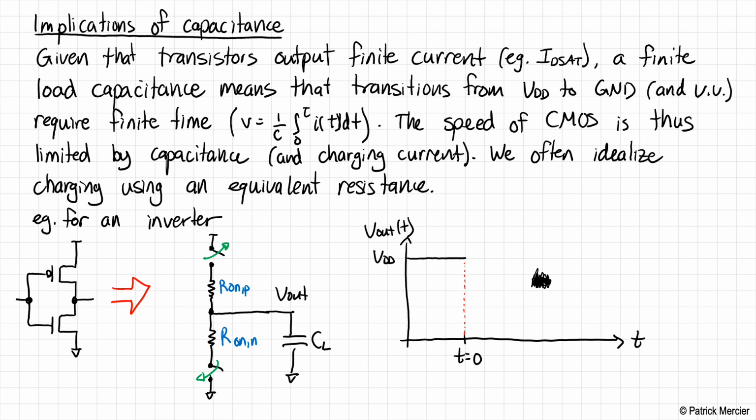We are representing the on resistance of the NMOS as an effective resistor, R on, N. Now, we know that in actuality, the resistance isn't actually fixed, because as the voltage of that NMOS transistor changes, the mode of operation of the transistor will change, and therefore its resistance will change. But to first order, we'll say it's approximately the same throughout the switching period.